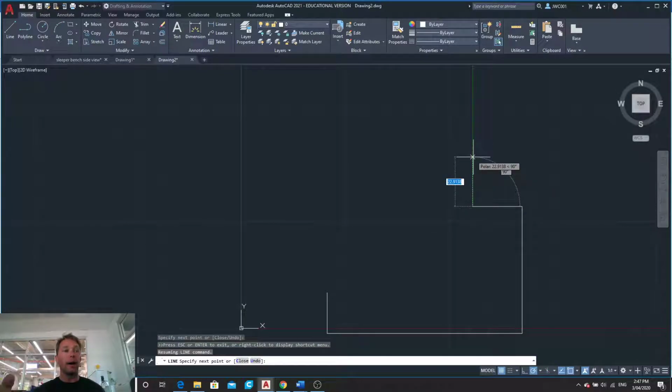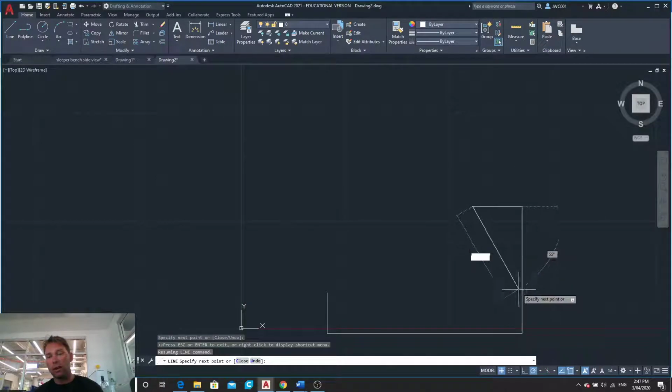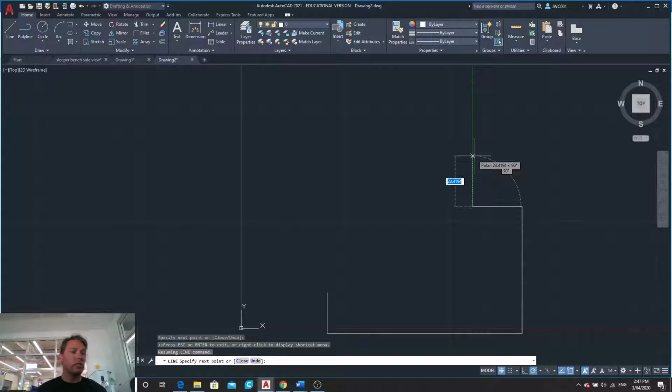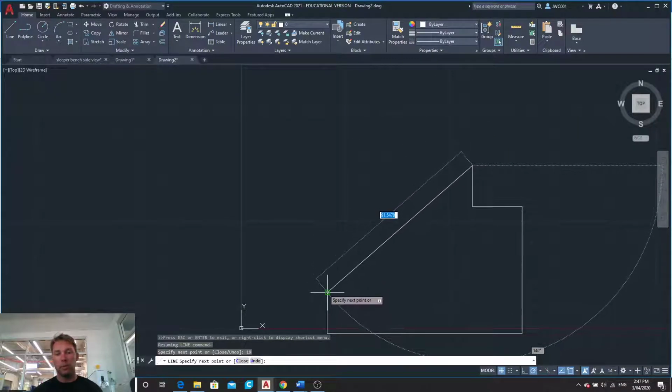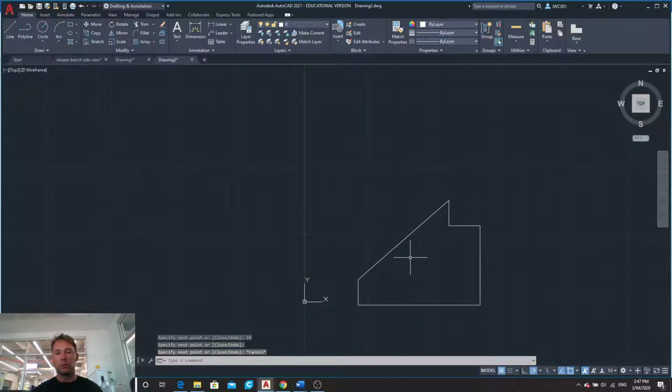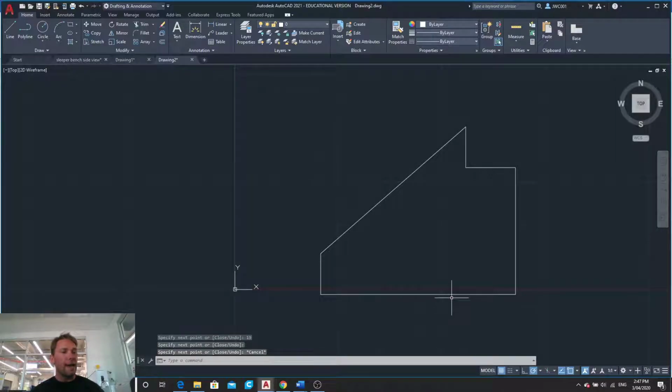And this is where I need to do a little bit of maths because on my drawing, it tells me the total height. It tells me the height of this line here. It does not tell me the length of this line. So I go, well, it's 78 mils high. This line to my right is 59 mils. That means 78 take 59, 19 millimeters. There's that one there. And now I just go back to this point. And there I have drawn the outside shape to the dimensions that have been provided.